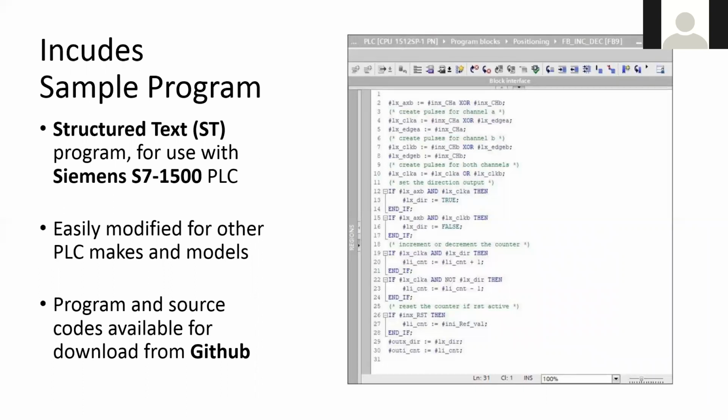And now, as with the first of the 24-volt models we looked at today, each of the workstations of the 24-volt variation of the Training Factory Industry 4.0 model have a relay board for motor polarity reversal and both a multi-pin connector, again, 34 pins with a grid of 2.54 millimeters for these particular models, along with PCB terminals with pushing connections for all inputs and outputs.